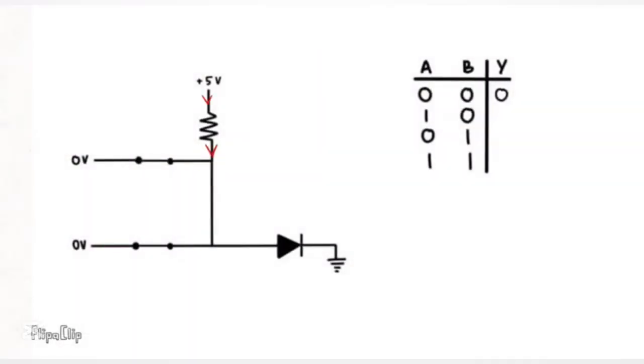Let's study the circuit for 0 input. The diodes will be in forward bias, so they act as closed circuit. First, the current flows through the resistor. Since the diode's voltage drop is lower, current will flow through the diode instead of LED to the ground.